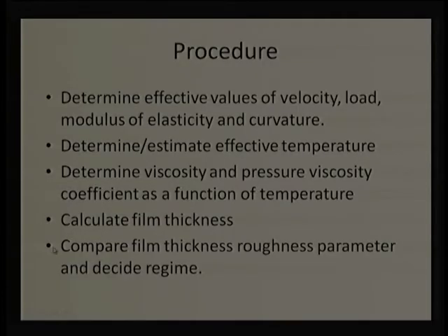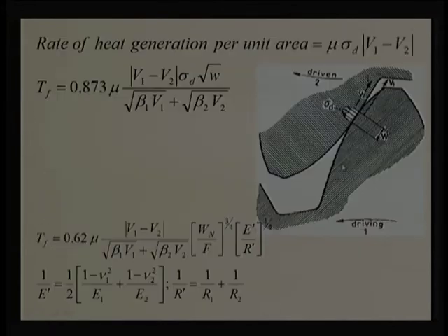So, it depends on the regime and a number of parameters that we can decide what the coefficient of friction will be. Again, we have given a big expression or big dependence, but those are indirectly affecting the coefficient of friction. We require so many calculations, that is one way, but we can go ahead with another way, which is that we can find out the effective temperature or maximum temperature or flash temperature at the gear interface using this relation.